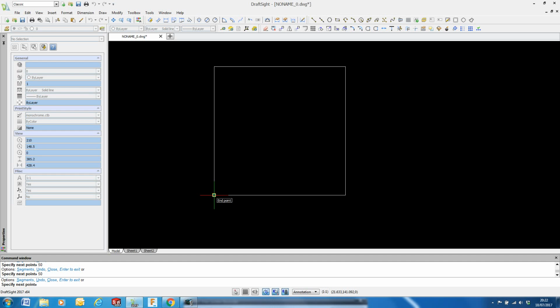Really important that we close lines correctly, especially if you're manufacturing directly from this data or something. Really important you don't leave gaps and you don't extend lines past where they're meant to end. But if you notice on this video, I can snap to the end point, and if I hover there it tells us the end point of this line, and that's my E-snaps.